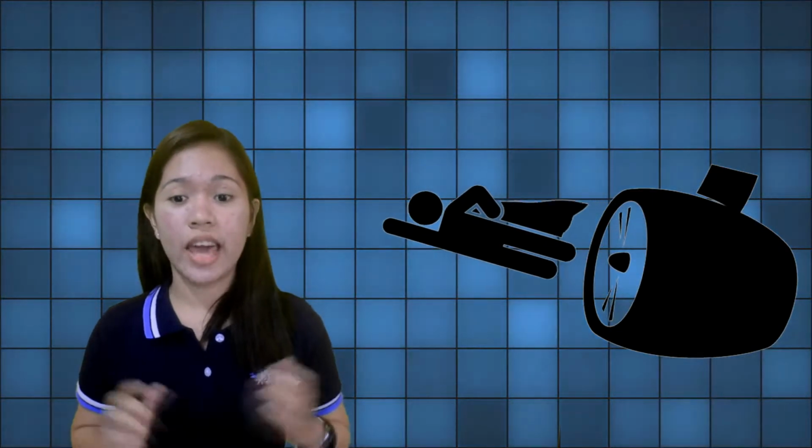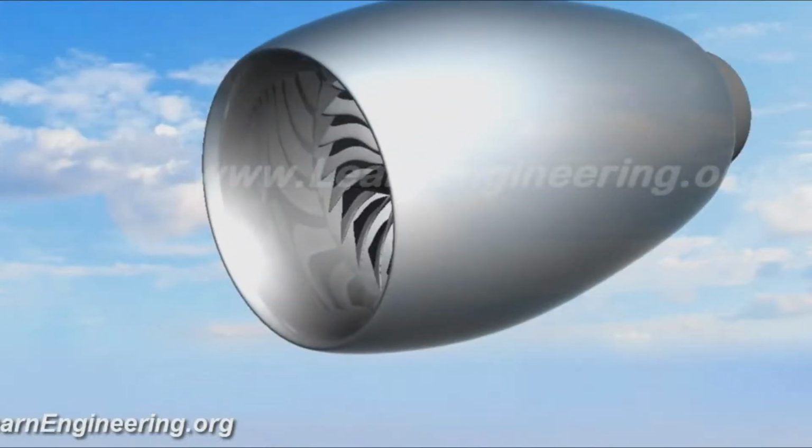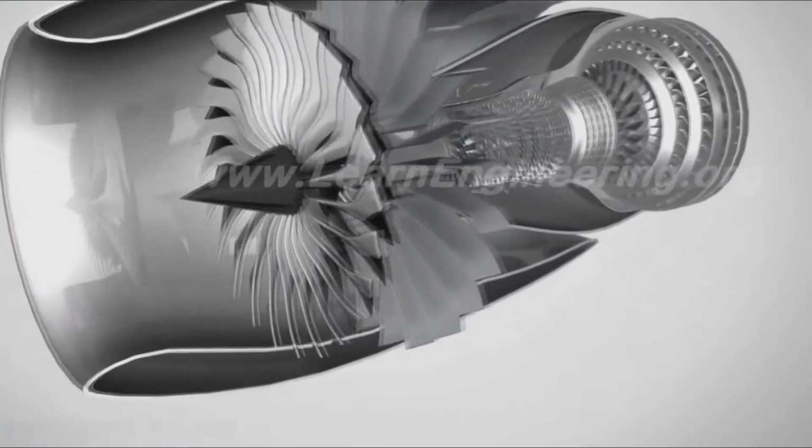Air-breathing reaction engines. What is a reaction engine? A reaction engine is a form of heat engine that produces thrust by heating a mass of air inside the engine and discharging it at a high velocity through a specially shaped nozzle. The amount of thrust is determined by the mass of the air and the amount it is accelerated. There are several types of air-breathing reaction engines, with the gas turbines being the most popular and useful. Engines with limited usefulness are pulse jets and ramjets.